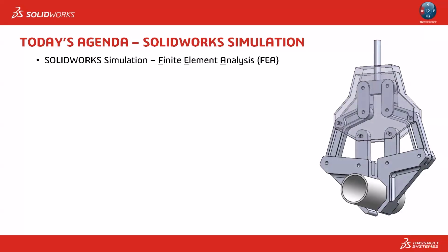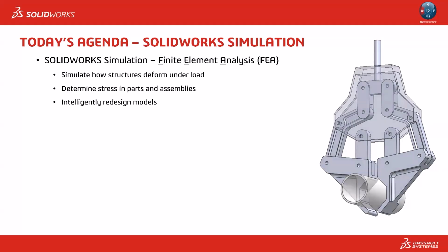And SolidWorks Simulation is a finite element analysis tool, FEA for short. The difference between the two is that Motion is a rigid body dynamics tool. The bodies don't bend and deform under loading conditions. They remain absolutely rigid. But with SolidWorks Simulation, we actually calculate the deformations that occur within bodies. So we can analyze how structures deform under various loading conditions. We can get stress and displacement plots and strains and this sort of thing for both parts and assemblies.